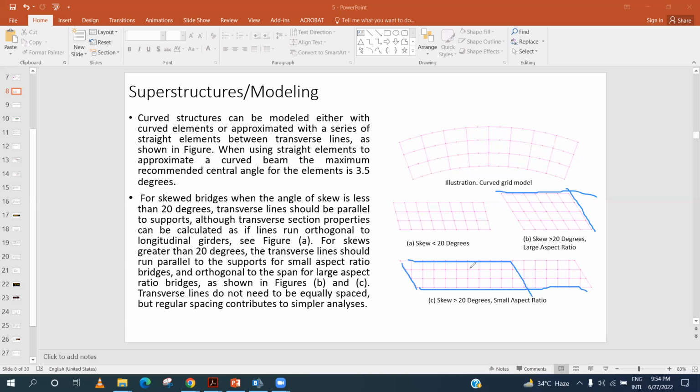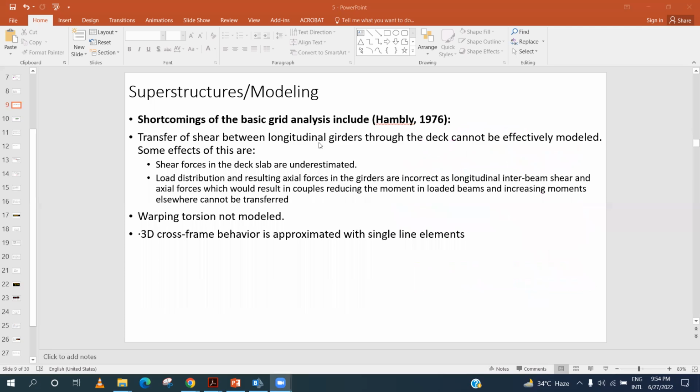So if you have a length greater than 2 or 3 times, then you can use this type of analogy. But for between 1 and 2, you can use this type of designing technique. I haven't done such grillage modeling, because mostly we use CSi Bridge for our design and it takes into account all these factors automatically.